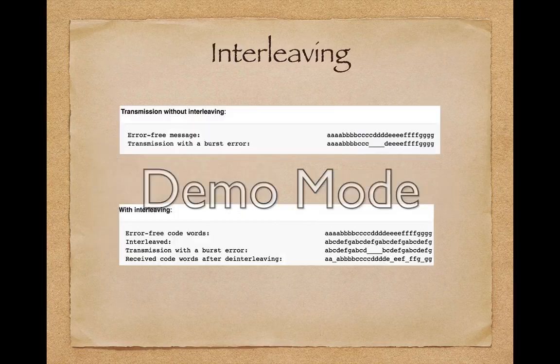Use of interleaving techniques increases total delay. This is because the entire interleaved block must be received before the packets can be decoded. Also, interleavers hide the structure of the errors. Without an interleaver, more advanced decoding algorithms can take advantage of the error structure and achieve more reliable communication than a simpler decoder combined with an interleaver.